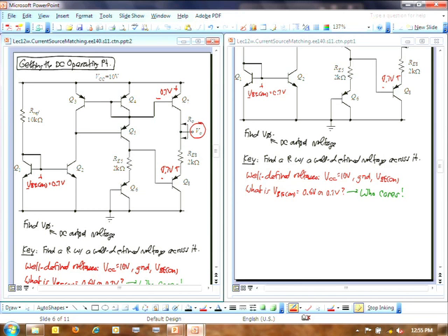So in general, can we always assume all the transistors are saturated? Exactly. That's the other thing you need to be careful with. I'm flopping around with my 0.7 volts, but you're exactly correct. You cannot say it's 0.7 volts if the transistor is cut off or saturated. Or sorry, this is bipolar. You can only do this if the transistors are forward active. So I should make that disclaimer there.